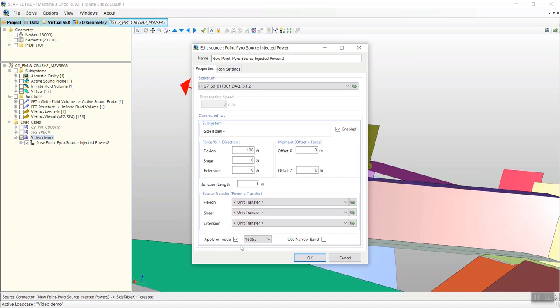The fact is, here I have two thick plates bolted together. One is 30 millimeter, the other is 50 millimeter. The side block, or the side table block, is 50 millimeter. And we are just at the intersection, so we don't really know the orientation of the driving point mobility, and regarding measurement, it's pretty sure that we need to use the right direction of excitation.